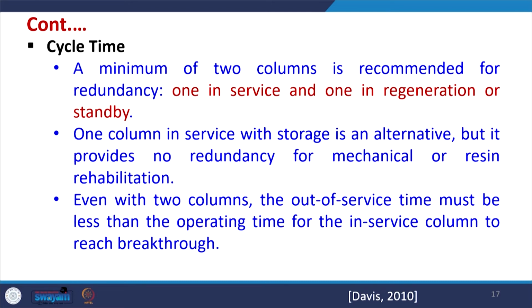One column in service with storage is another alternative which is possible, but it provides no redundancy for mechanical or resin rehabilitation. Even with 2 columns, the out of service time of a column must be less than the operating time for the in service column to reach breakthrough. So, this is very important in design: the in service column should work for a longer duration as compared to the out of service column for regeneration.